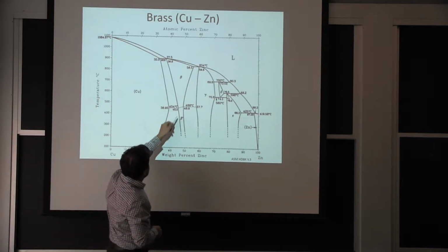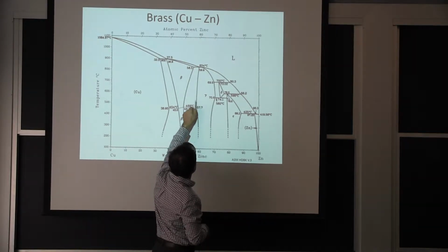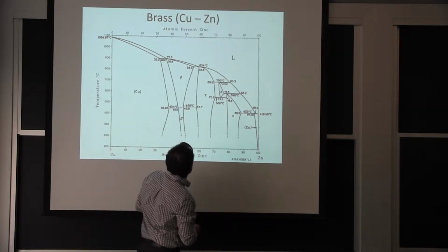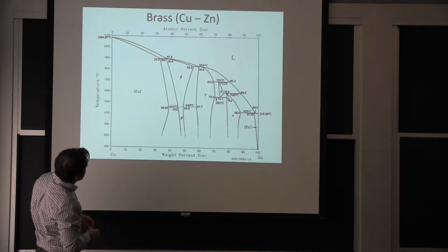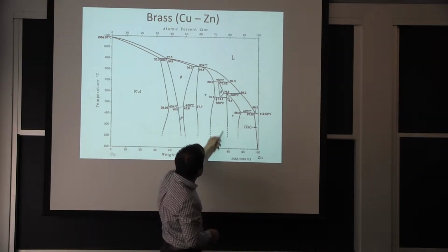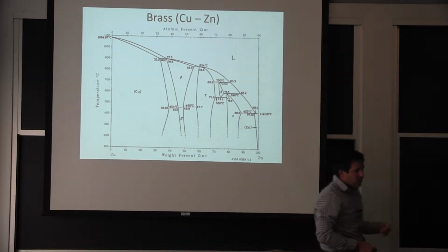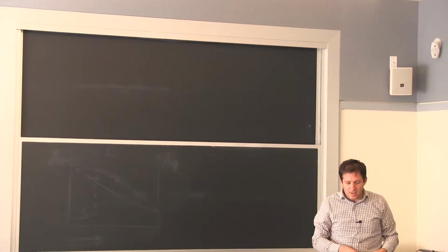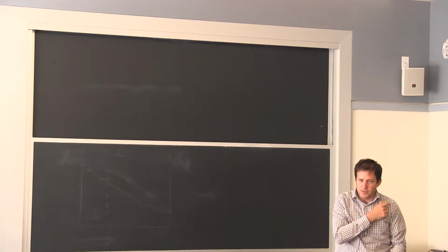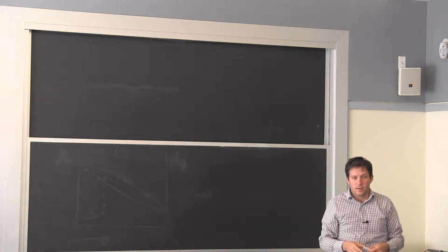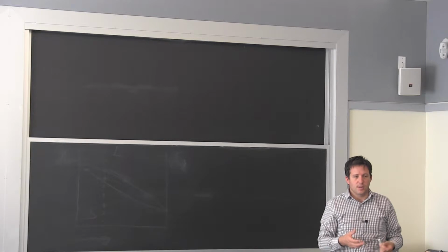So if I'm anywhere between this region and this region is where I have a little bit of both. There's a range here. If you see there, you have some periodic transformation. You can go from a single phase to 2-phase. There's a possibility with this situation to get some hardening the same way we've talked about. It's not used a lot. It can be used in any alloy that you find a transformation that you can delay and then find a very fine microstructure that you can do dispersion strengthening. Yeah, you could do it. It's just a question of whether it's important.